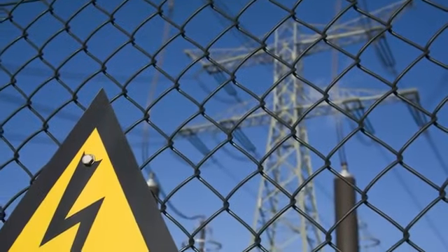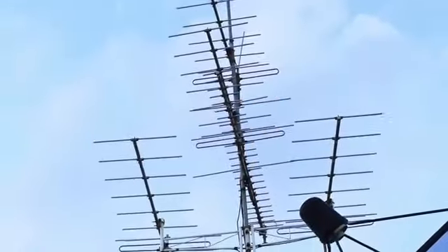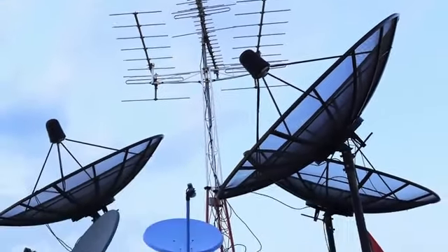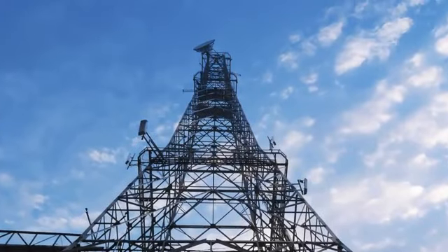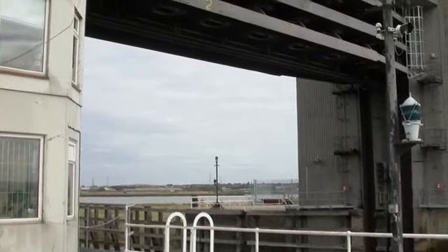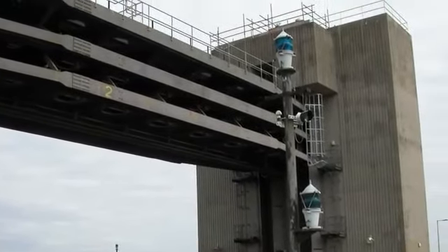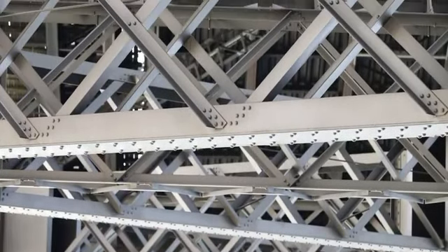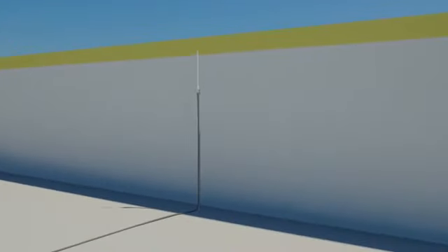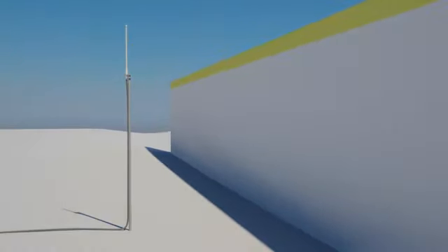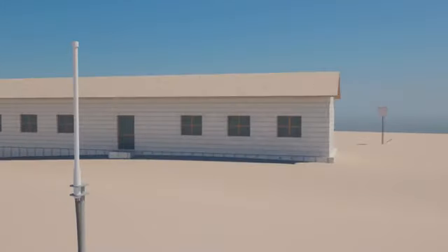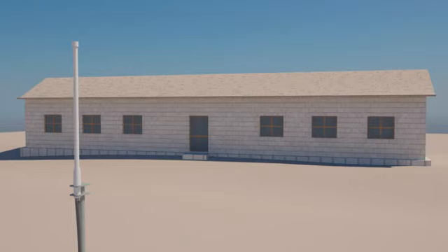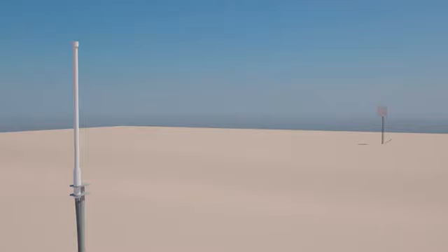The next crucial consideration would be keeping other electrical objects away, having clear line of sight, and having proper antenna direction. Not only is the relationship between the antenna and the earth improved by mounting an antenna higher, resulting in better ranges, but the probability of interrupting the line of sight is reduced. You should avoid mounting next to solid objects such as walls, buildings, towers, or girders. The resulting reflected radio energy causes drastically reduced efficiency. A minimum of 6 feet is a good general rule to avoid excessive reflection. When considering the signal path, keep in mind that obstructions that block the path can greatly deflate the radio carrier wave because of the frequency range used in operation. Try to minimize obstructions such as trees, buildings, hills, and so forth.